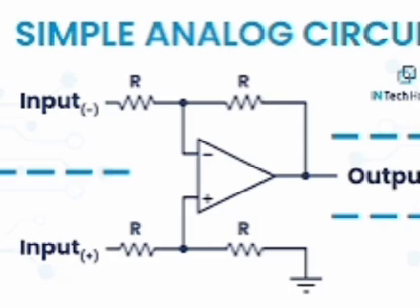Ripple factor of half wave rectifier gamma equal to 1.21. Crest factor of half wave rectifier C equal to 2. Form factor of half wave rectifier F equal to 1.58. Efficiency when RS equal to RF equal to 0, ideal case, eta equal to 4 by pi square, that equals 40.6%. Peak inverse voltage for half wave rectifier PIV equal to VM. Transformer utilization factor TUF for half wave rectifier equal to 0.286. Output frequency equal to input frequency for half wave rectifier.